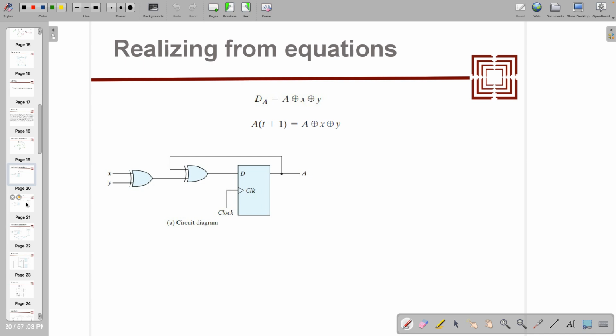Now the next thing is you need to write down the state table. Can we write down the state table? Present state, you please write down. Present state, I need the following: present state is A(t), next is A(t+1), when x equal to 0 and x equal to 1, and what is the output? That we need to write down.